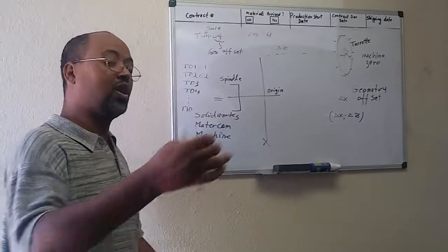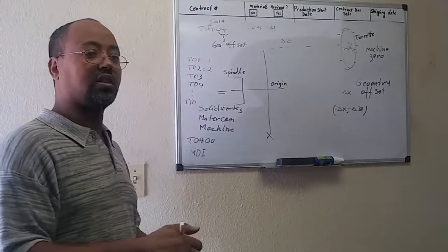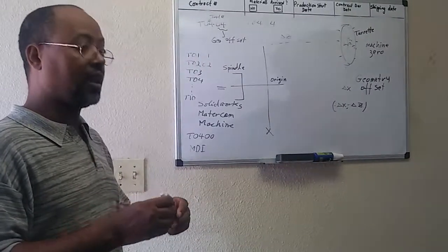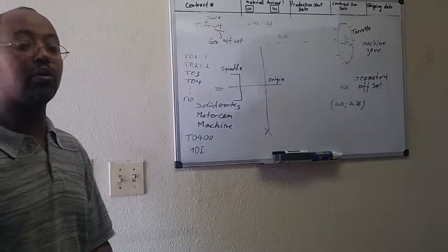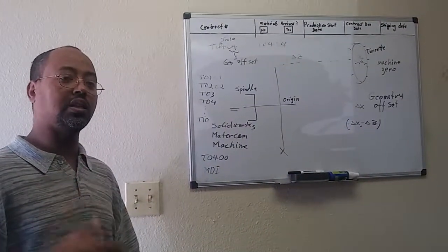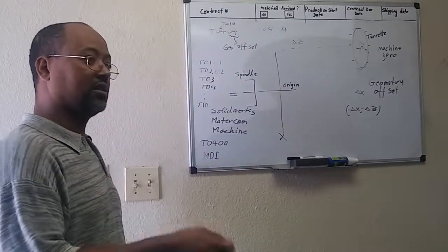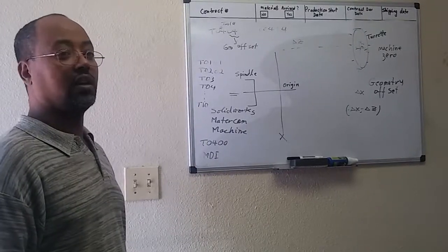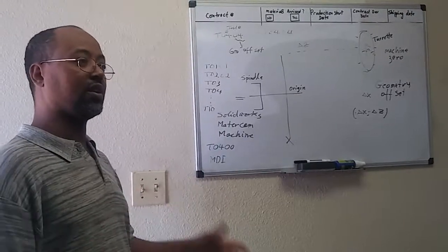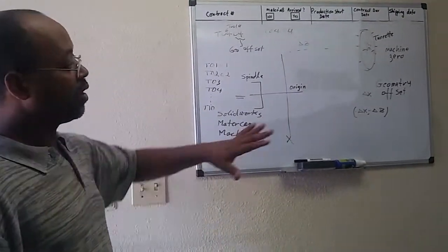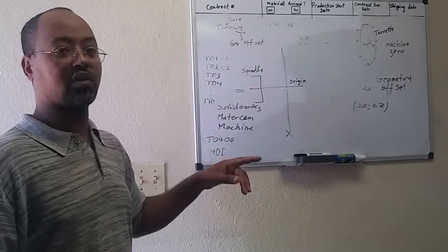Now you have to go to its respective location and bring it to the origin. And that is kind of like hands-on training today. Daniel and David were here yesterday all day. They know exactly how to do it. But it's not that easy, because sometimes you have to move everything manually. You're going to use the handle to move around your turret. You have to use some switches, so you're going to have to do it over and over so that it will sink in. But right now we're just explaining the basics: why do we have a geometry offset, what is the purpose of that.